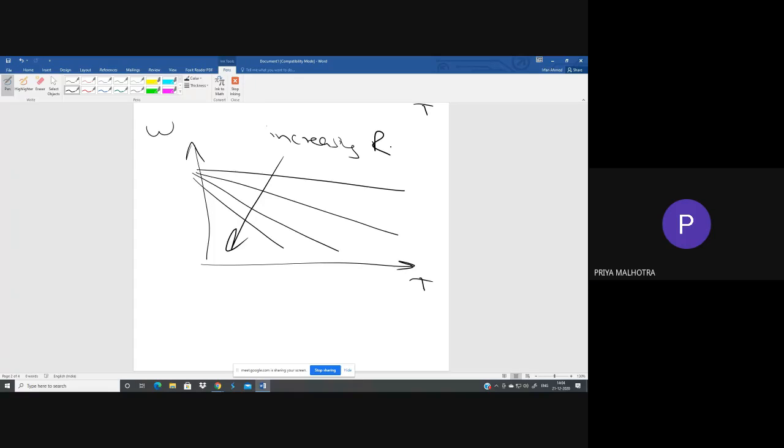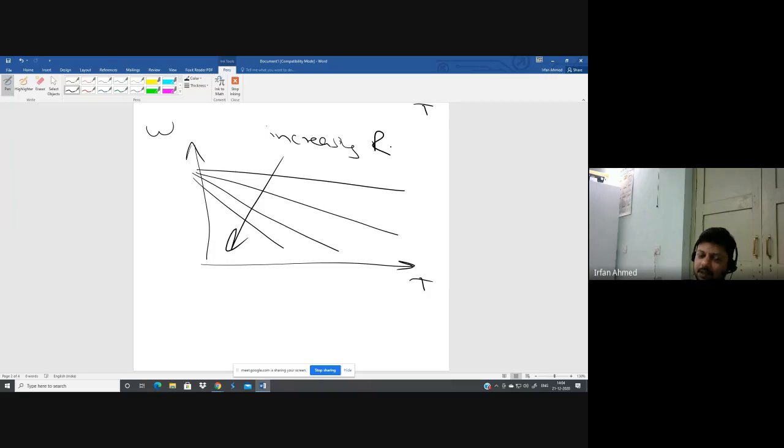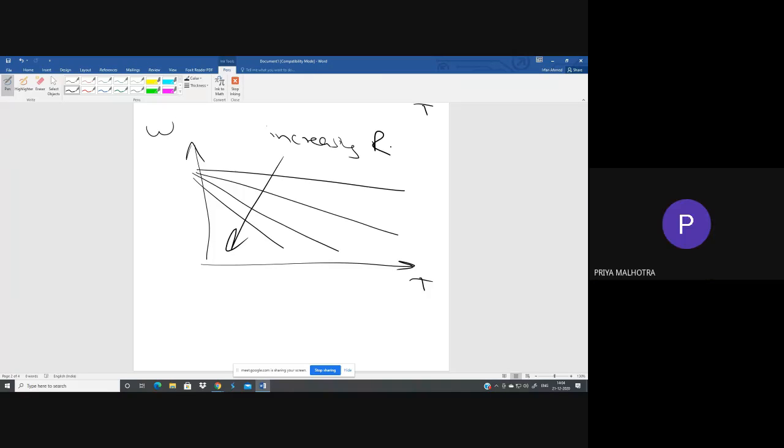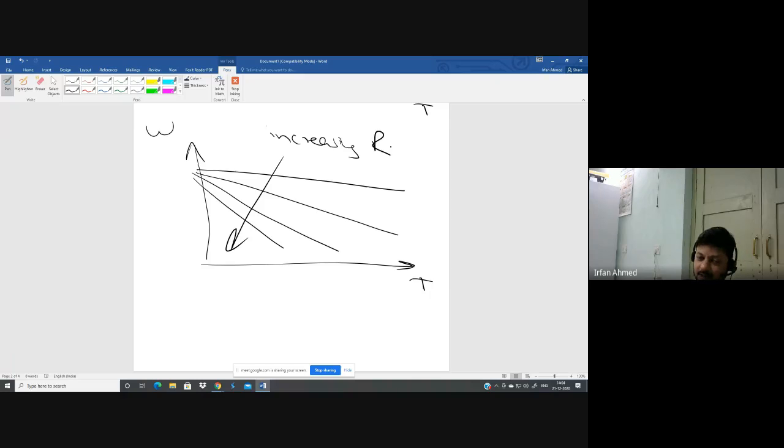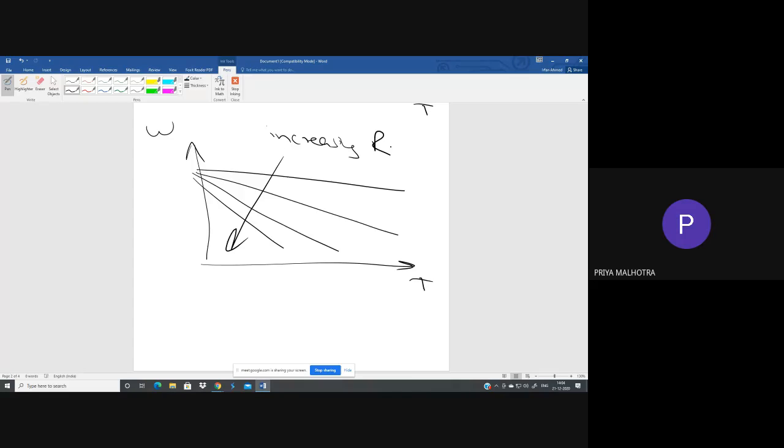Speed is proportional to E by phi. Speed is proportional to E, which means V minus IA RA. So IA is equal to V minus E upon RA.